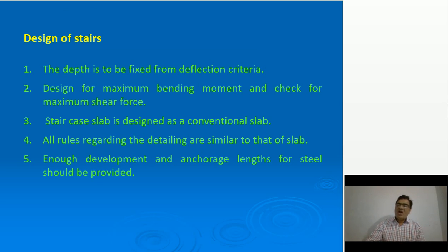Well, now how to design a staircase. Already we saw design of slab. Design of staircase is almost the same, only some of the points vary, which we'll discuss here. The depth is to be fixed from the deflection criteria, so we consider the L by D ratio. According to the L by D ratio, you have to decide the depth of the base slab.